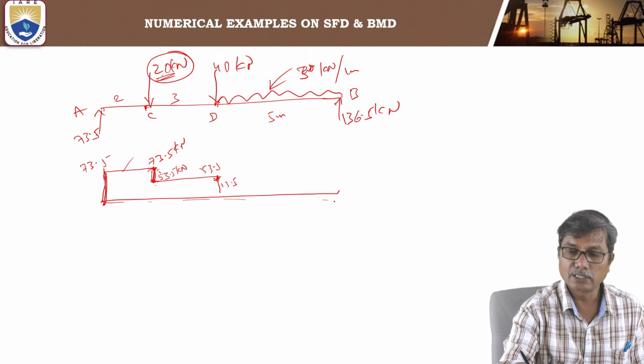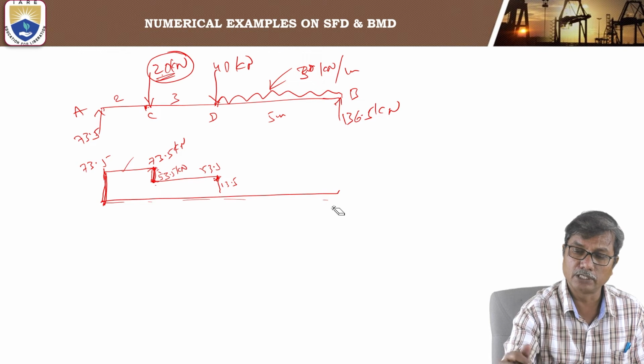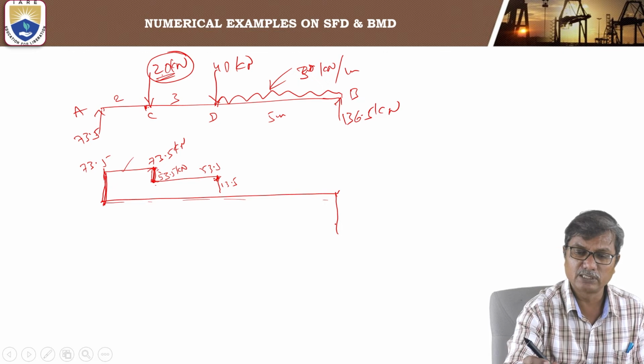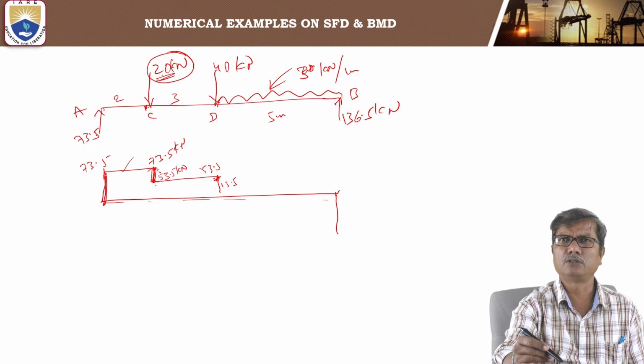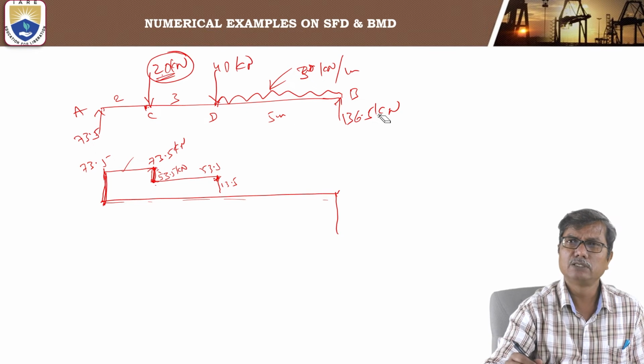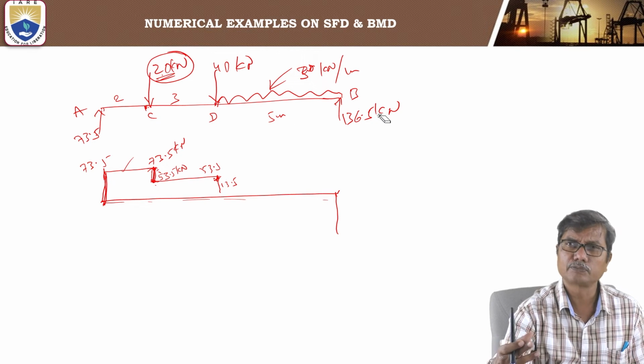Even without calculating, you can plot the shear force diagram, but not the bending moment diagram. The shear force diagram can directly be plotted without working out all those. Just by finding the reactions, we can draw the diagram.